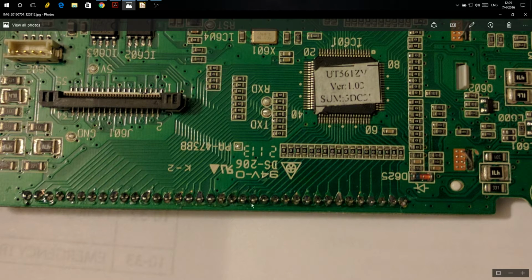And the way you can really test, or find the segments, is you have to find commons and of course the segments. All the segments are tied to buses internally for common segments, and so this one has 4. So you'd have, say, this pin and this pin will do a segment, and this pin will do a segment somewhere on the display. So this one has 4, and these pins over here correspond to segment 0 through 3, or just common 0 through 3 in this microcontroller. It's just fantastic that it turned out that way, because it makes things simple.